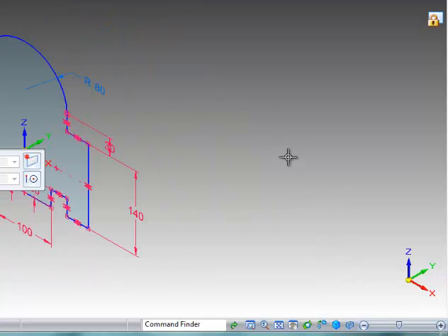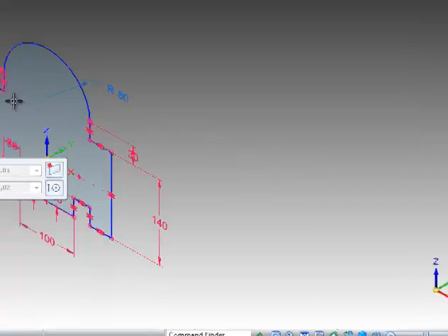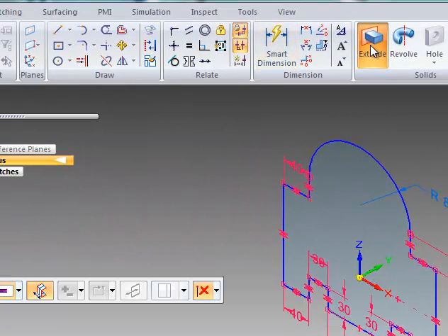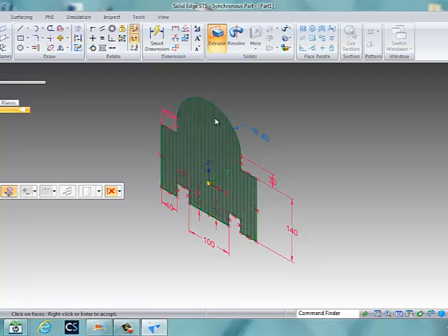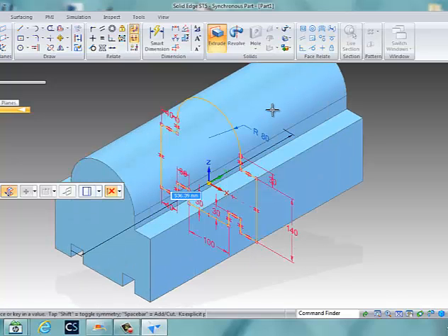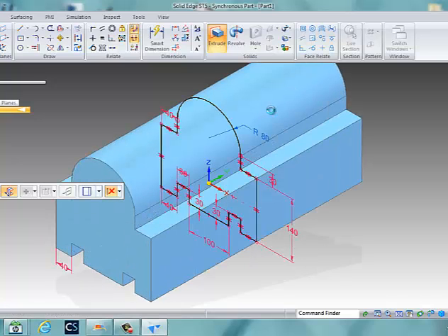Excuse me. And we're going to go ahead and extrude this. They don't give us a dimension in the book, so I'm going to call it 120. We want a dimension that extrudes in both directions symmetrically from the center line. So I'm just going to left click on this, hit enter, pull it out. We'll key in 120.